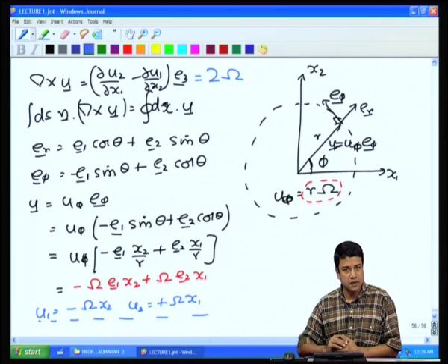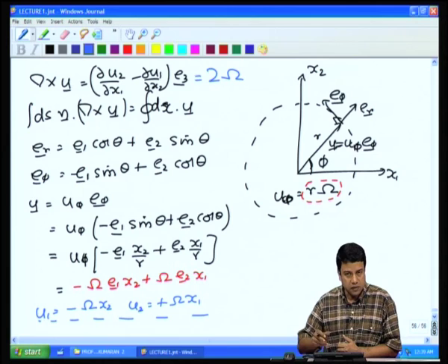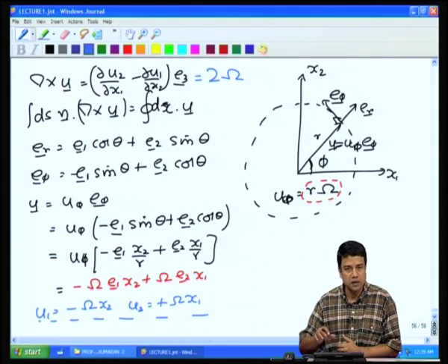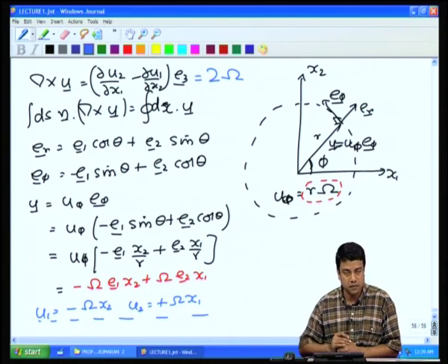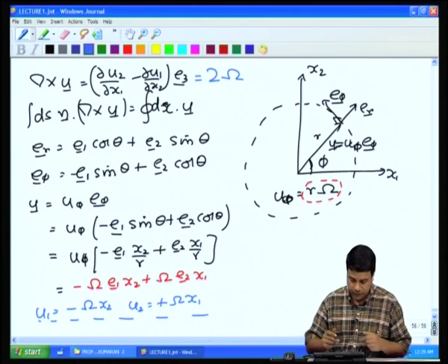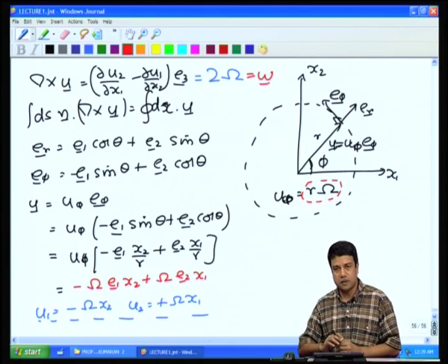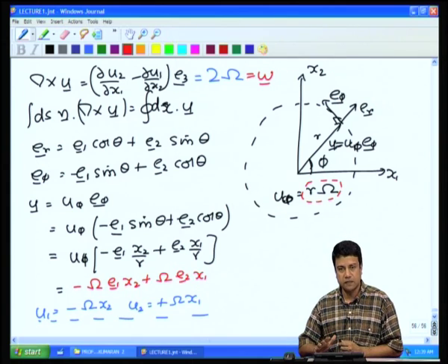So, the curl of the velocity field at a point for a solid body rotation on any contour, note that this curl that I got for this solid body rotation is independent of r now, it is independent of distance from the origin. It is perpendicular to the direction of the velocity variation and it is equal to 2 times the angular velocity. Okay. This is also called omega, the vorticity, the local vorticity of the flow. So, the solid body rotation is equal to half the local vorticity.